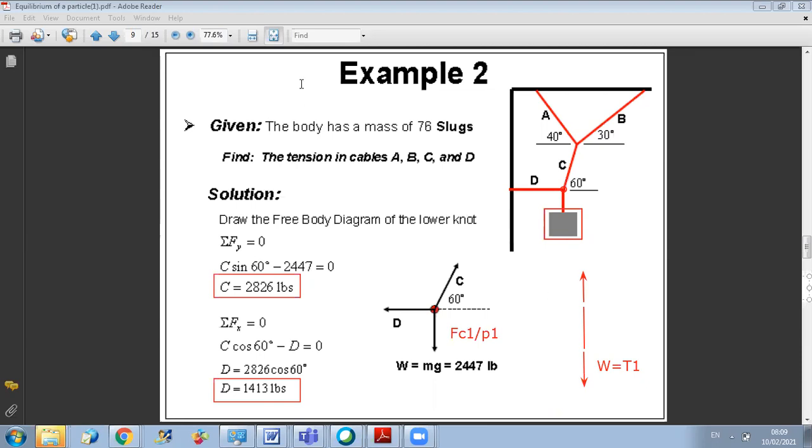This is why, if you represent the force of cable 1 on the point, it will be downward. And always, because any cable is in tension, the action of the cable on any body will be directed towards the cable. So if we do similar analysis, cable 2 will act on the point like this, because the point will act on the cable outward.